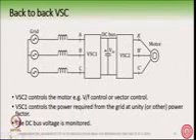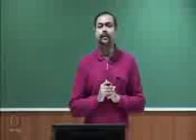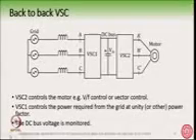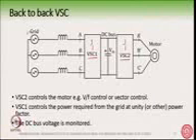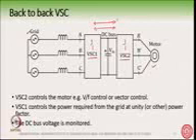Okay. So in the last slide I talked about the diode rectifier having this problem that it cannot feed back the energy into the source and the capacitor voltage will go up. So to get rid of that problem, here we see that we are using two VSCs, VSC1 and VSC2, made up of switching devices. So this is a bidirectional converter. On this side you have the grid, there is a DC bus and there is a motor. This is also called the back-to-back VSC because the active and reactive power can flow seamlessly from left to right or right to left, at different frequencies. So this is say 50 Hertz, this can be 25 Hertz, but it can also be 50 Hertz. So it can flow seamlessly.